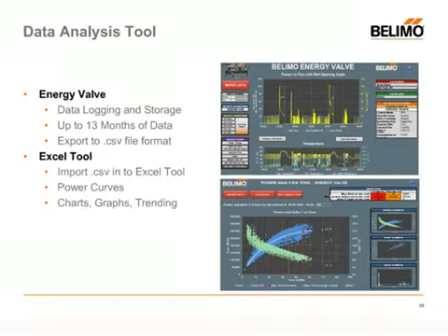Now, this here is the data analysis tool, and this is provided free as well with the valve. And this is used for the data that's stored, that 13 months worth of data that we talked about, which is stored on the actuator. That's exported out of the actuator, imported here into the data analysis tool. Now, the data exports out of the actuator in a CSV file format. And for those of you that are not aware, that's a comma separated value.